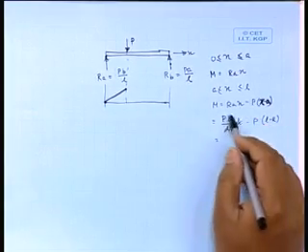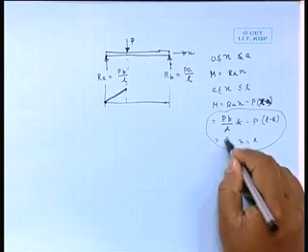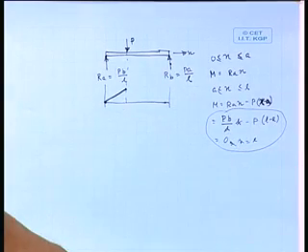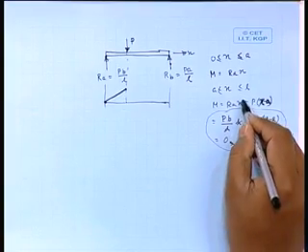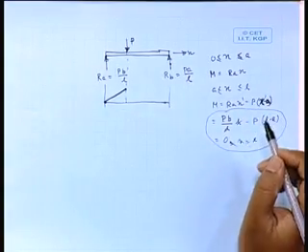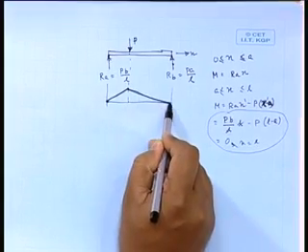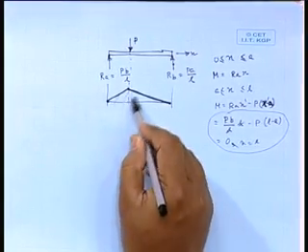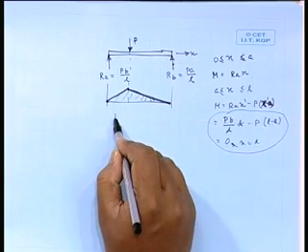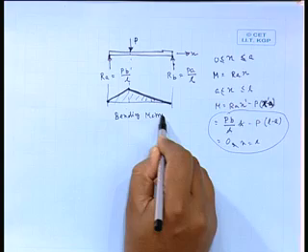So at the right end, if we put x equal to L, the whole quantity will lead to 0, and it will follow in a linear manner because it is x to the power 1. Automatically it will come down to 0. So this will give a diagram, and this diagram is called the bending moment diagram.